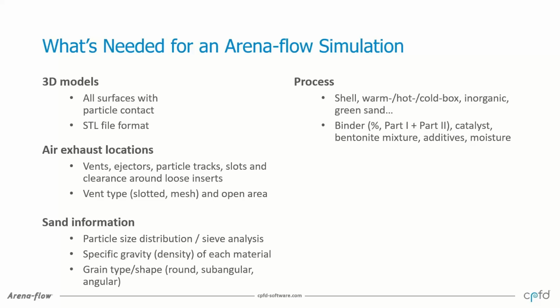Last but not least, we would like to know what kind of process you want to simulate. It's cold box, warm box, hot box, green sand, or inorganic, as mentioned prior by both Peter and Niraj. We need to know the binder, again, it's viable for flowability.